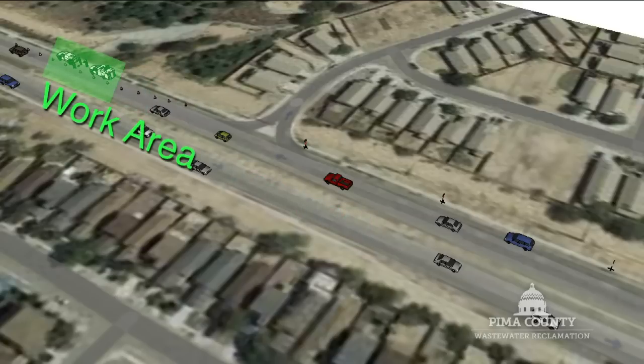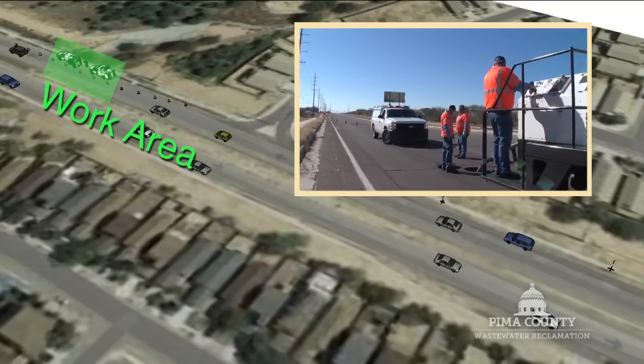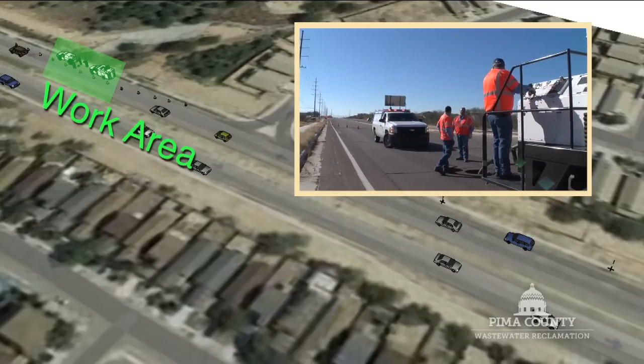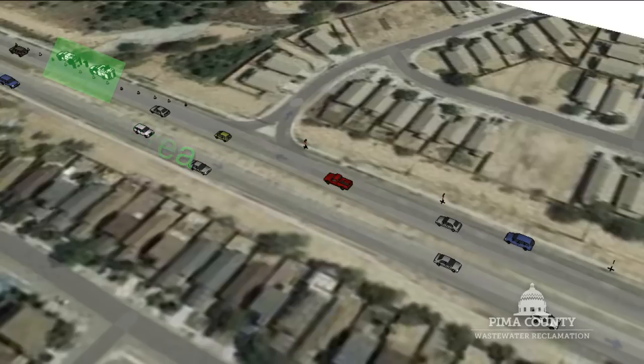The work activity area is the portion of the roadway closed to traffic and set aside for workers, equipment, and materials. The workspace within the activity area may be stationary or move as work progresses. A support vehicle with a truck-mounted arrow board stays behind the vehicle performing the work. The termination area is the area where traffic is returned to its normal path.